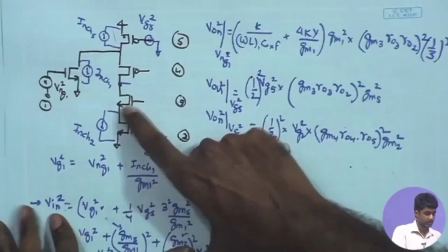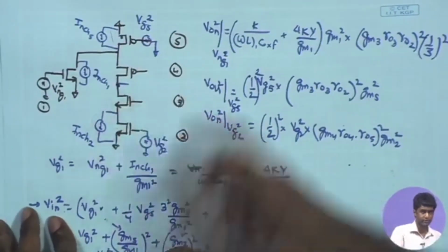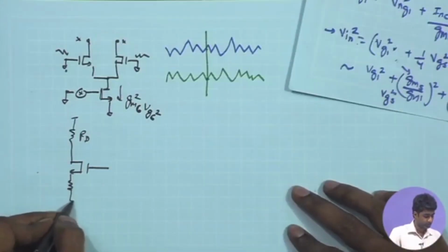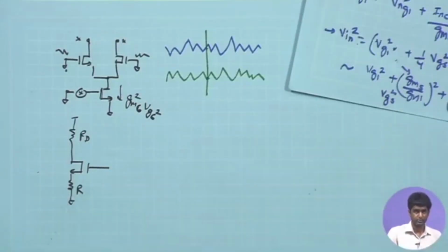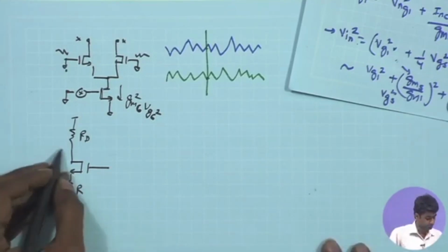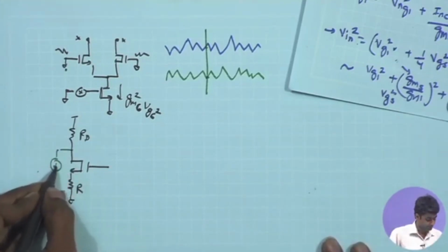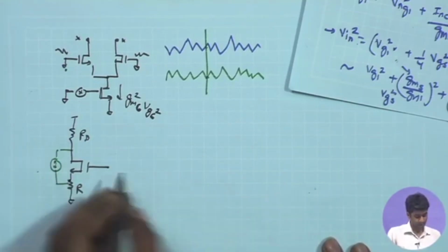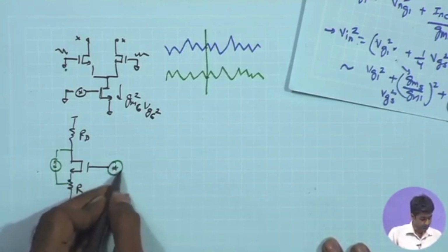Likewise, M3 is also having a large resistance in the source, which is RO. So I can call it RS. So of course, RD is much greater than RS in this condition. And then on the top of that, we have the noise contribution because of this channel current, if we can assume it. And then you have an overall signal, the noise signal at the gate.